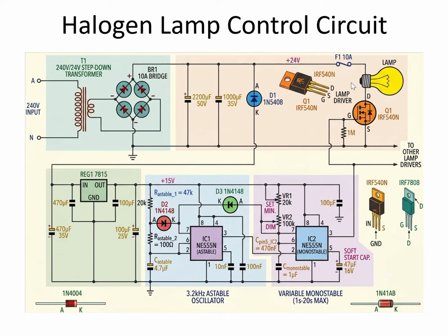So we can see from the circuitry that whenever the MOSFET is turned on, only then the lamp will glow. Otherwise, the lamp will not glow, because this creates an open circuit here due to the off condition of the MOSFET. So whenever the gate receives a high signal, the lamp will start to glow. For a longer pulse width, the lamp receives more power and provides higher brightness. For a shorter pulse width, less power is received by the lamp and it provides very low brightness.